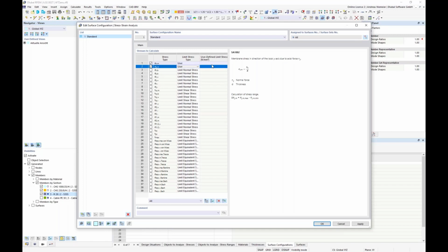So you can take from your biaxial test what you get from your manufacturer, the failure test strength. Here, for example, let's use 30 MPa and 26 MPa for the weft direction. And you see how it's calculated with this formulation here.